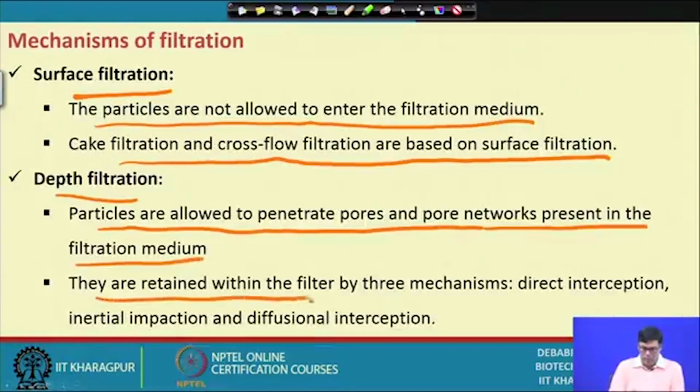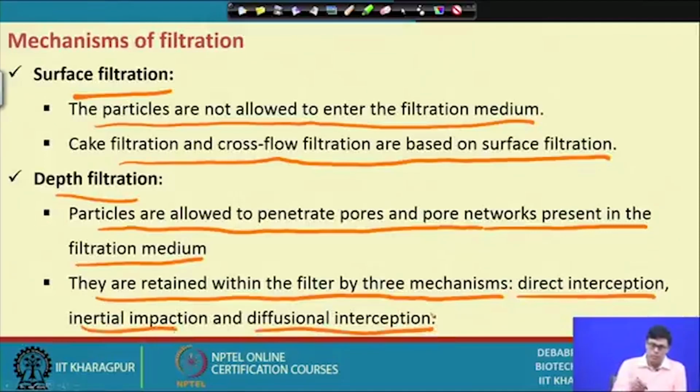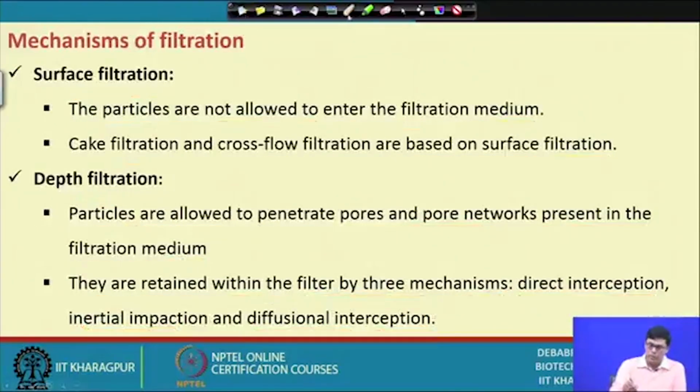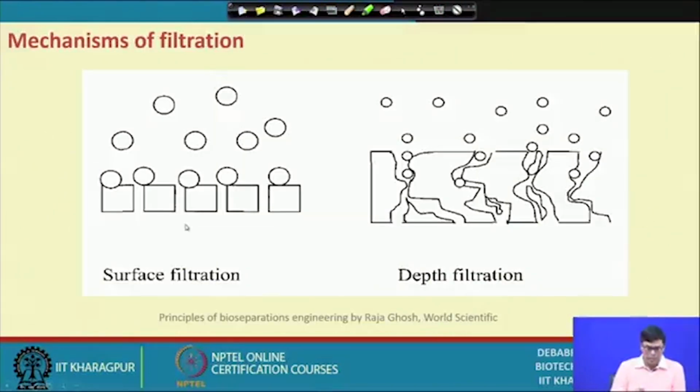They are retained within the filter by three mechanisms: direct interception, inertial impaction and diffusional interception. I explained all these principles during the air filtration process. Some material is entrapped inside, like in the air sterilization process. In surface filtration, the particles remain on the surface of the filtration media.